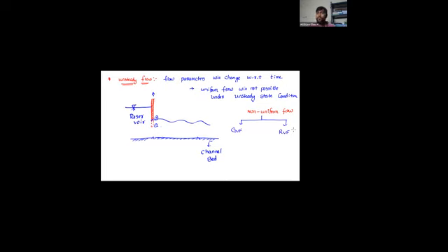Okay. Now, once you drop the stone, do you think the waves are going to be produced there itself, or they are going to be produced along the length also? Do you think the ripples are going to travel along, or are they going to be formed there itself? When you drop the stone, the ripples are going to travel. So at that particular instant or section, the water level fluctuates, and it is going to fluctuate over the length. So my dear, observe here clearly, unsteady flow, and this variation is happening over the length. Unsteady non-uniform flow, because along the length also the water level is going to fluctuate.